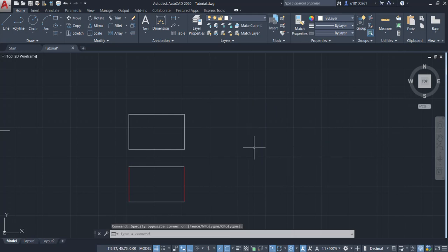So what's the difference between them? You can note the difference when selecting, comparing a drawing that is drawn using the polyline option with a drawing drawn using the original line option. This is a rectangle that I've drawn using the original line option; when you press on any side, it does not select the whole object. But compared to the one above, if you press on any side, it's going to select the whole rectangle.